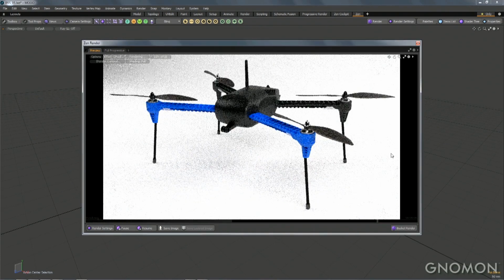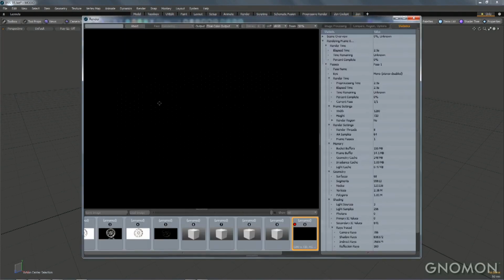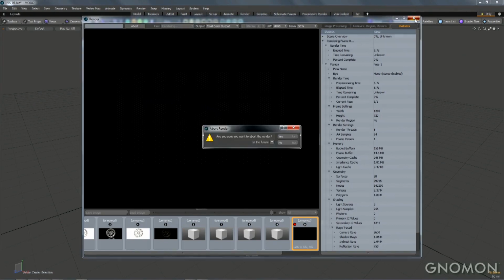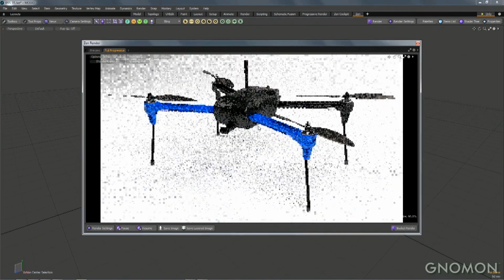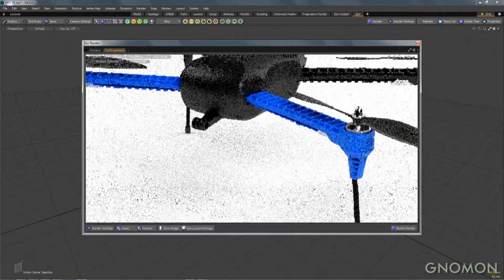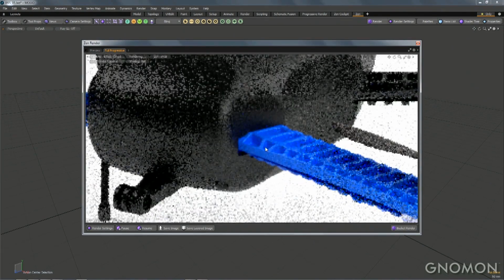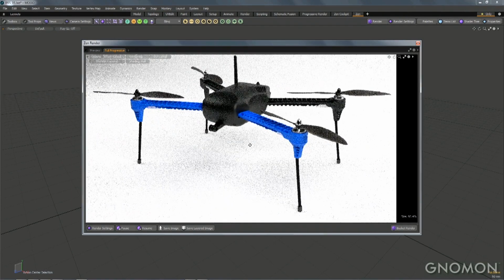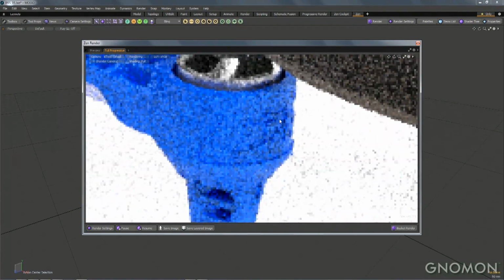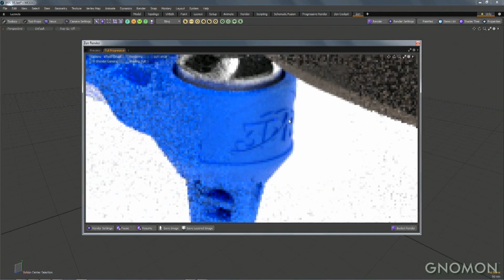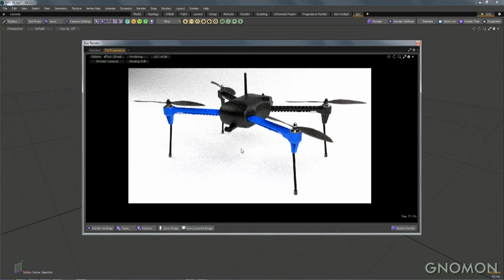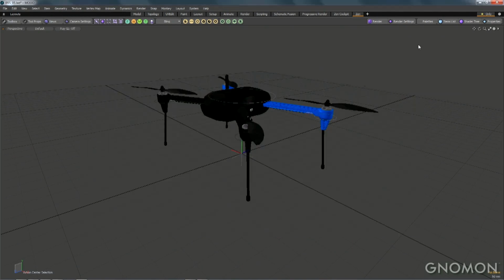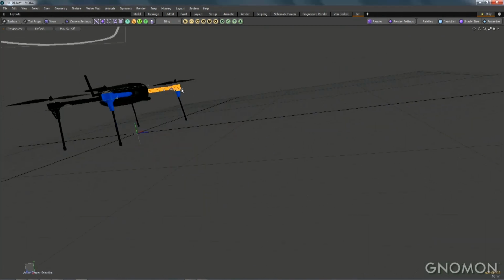And now I can jump here in the rendering UI and click on bucket render if you want to use the bucket renderer. But for still images, and even increasingly for animations, you don't even need the bucket renderer. Don't futz with that. Just go to the full progressive, let it run, and the image will be fantastic. And of course, with all of these progressive renders, it's going to chug right under your mouse first and foremost. So if I just zoom into this part, I can get a quick preview of what the final image looks like and see that, oh, I forgot to add the pad print to this logo. So we can close this up and go back and start to make a change.